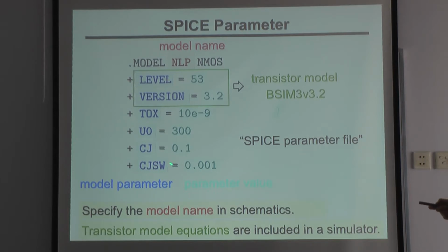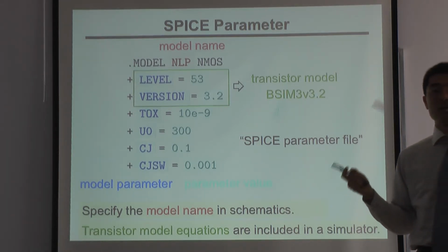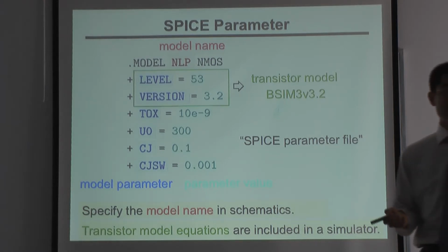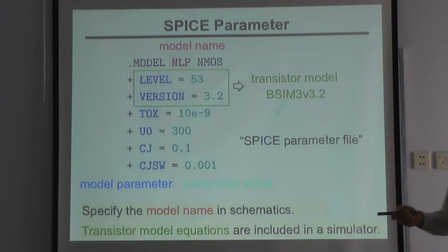I call these model parameters, and these are parameter values. In the schematics, we specify this model name. Usually, once we have all these parameters, transistor models are automatically included in SPICE simulators, so we don't have to care about what kind of equations we use. But we have to care about what kind of model we use.